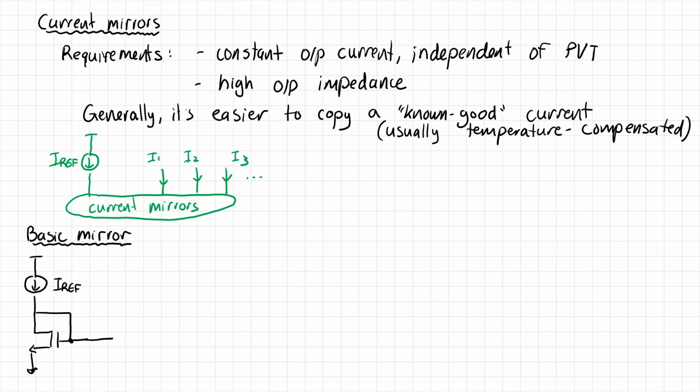And we take this through to another transistor, which then pulls the current off. So we'll call this here I out. This node here is Vx, and we'll say that this transistor has a W over L ratio of 2, and this is W over L 1. Okay. Again, if you've studied analog circuit design before, this should be a very familiar structure to you.